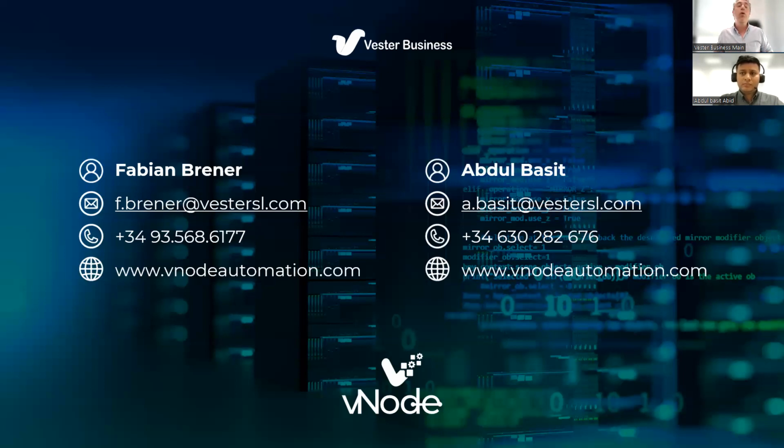The main goal of vNode is not to connect to as many devices or as many protocols as exist, because vNode can be an OPC UA client, so there will always be an OPC server to connect to something. It can be Matrikon OPC server, or any other. For example, if we're talking about EtherCAT, we're talking about the Beckhoff OPC server. So the best way to collect the data in vNode from EtherCAT will be using the OPC server from Beckhoff in this case.